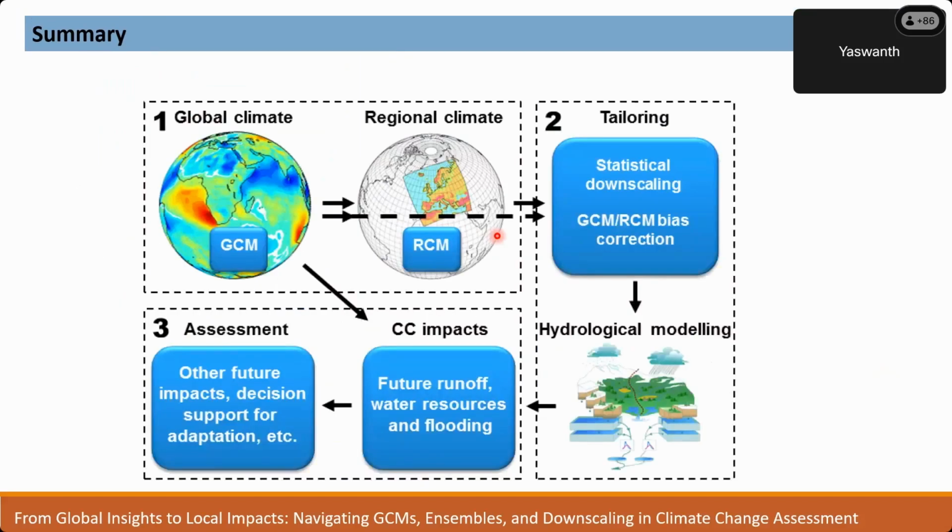So in summary, what we have discussed is global climate models and regional climate models. The regional climate models focus on the region of interest, and we wish to run them at very high resolution if we have computational power and storage capacities. Regional climate models run considering the atmospheric physical processes. But statistical downscaling usually considers regression techniques or our own statistical methods to establish relationships. They may not consider the physics of the atmosphere well, but they are computationally less burdensome. The main motto of downscaling to higher resolution, or bias correction, is to provide high resolution input to the hydrological model to have better predictions.